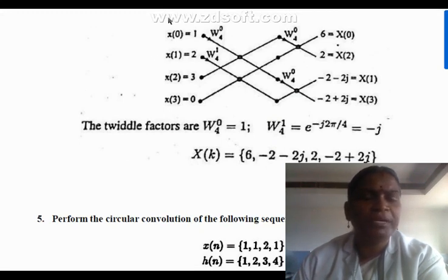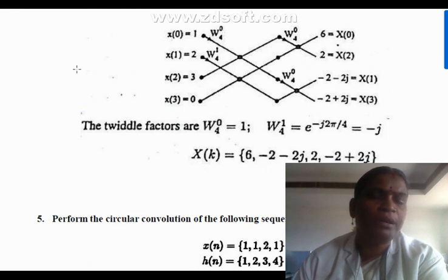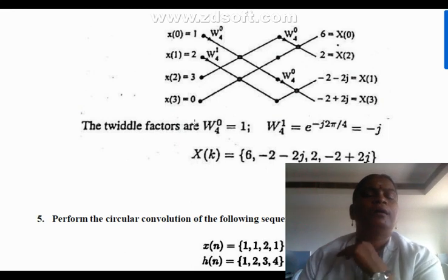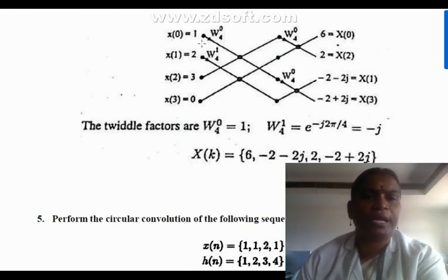It means that we have to follow bit reversal in the DIT method. Bit reversal means x of 00 again is 00. The bit reversal is the same as our common method. And 01 we have to convert to 10, which is bit reversal. So we have to write 2-bit variations, which means we have 4 combinations 0 1 2 3. In the bit reversal we get 0 2 1 3, so we have to write the problem in bit reversal order initially.